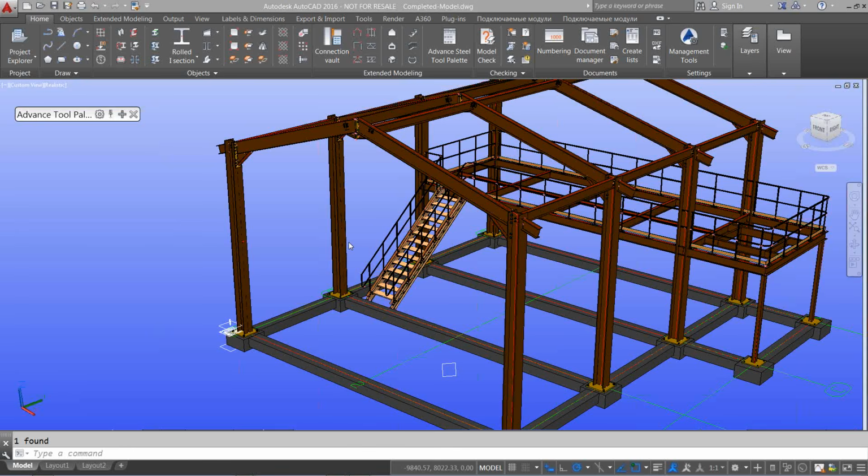Can we import a model from Advanced Steel into an Inventor assembly? Okay, look, I would actually go the other way around. I would bring the Inventor stuff into Advanced Steel. Inventor objects can be exported as DWG solids and brought into Advanced Steel, and they are treated as external components. They can be included in your drawings as well. This is the discussion that I had with someone else as well. I would rather get Inventor vessels and things like that, could be conveyors or whatever it is, into Advanced Steel, not the other way around.